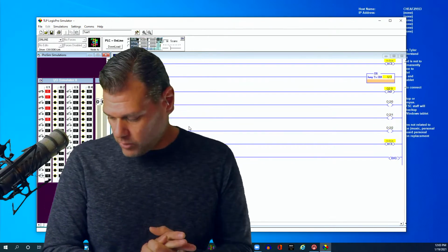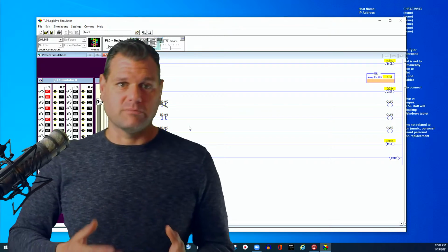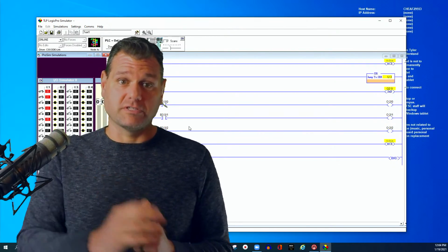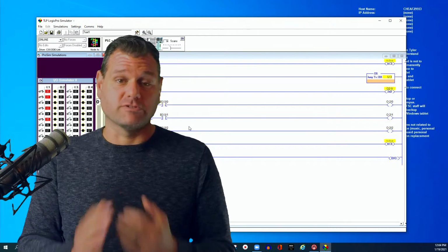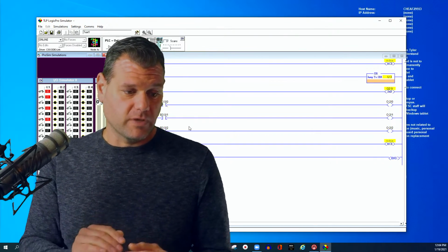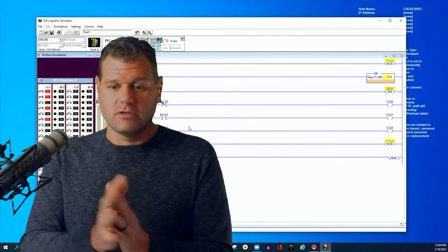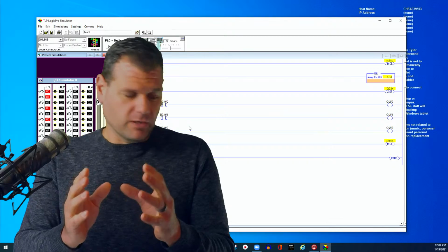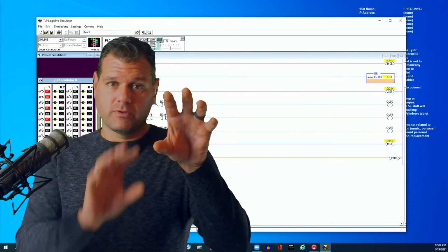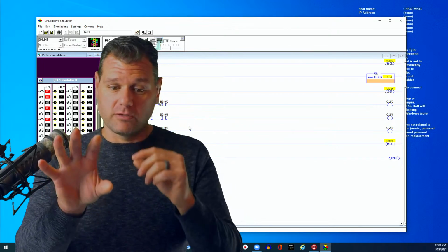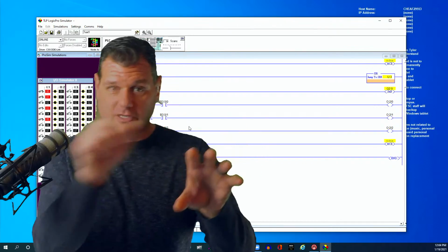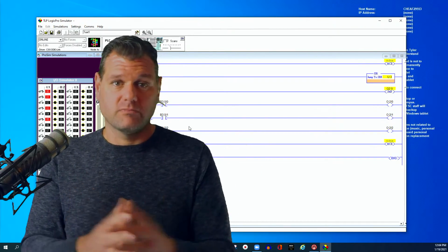Yeah, we're on page 193, which is going to do immediate inputs and immediate outputs. And it'd be very hard for me to demonstrate this on screen because it happens so fast. Like I was saying earlier, we have 4 basic parts, and we'll take a break here in a second if you guys want to just stretch your legs. But basically, the 4 parts: read inputs, scan the program, update the outputs, and then do your housekeeping. So you've got the four pieces that make it logical.